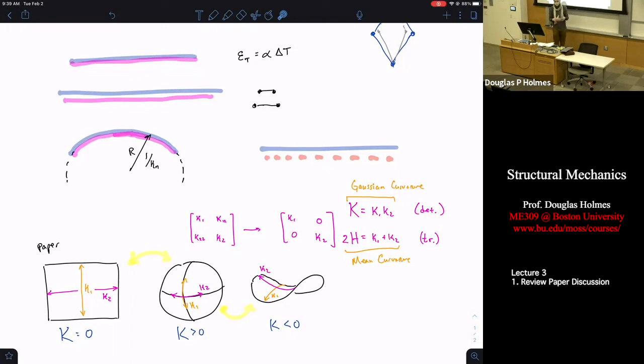So what happens to your baking sheet is it's differentially heated. It tries to warp into a sphere. That becomes so energetically costly that it buckles. And what does it buckle into? Well, it has to be curved because you're heating it up, so it's trying to curve. And so what it does is it says, I can't buckle into a sphere, I'm going to buckle into a cylinder.